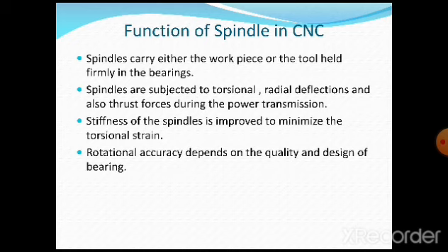If you take the rotation of the workpiece, it is carried out by mounting the workpiece on the spindle, and the accuracy of rotation of the spindle plays a major role in the workpiece rotation. Similarly, the cutting tools mounted on the tool turret are also indexed. So even the tool turret head is mounted on a spindle, and the bearings are responsible for supporting the spindles. That is very, very important.